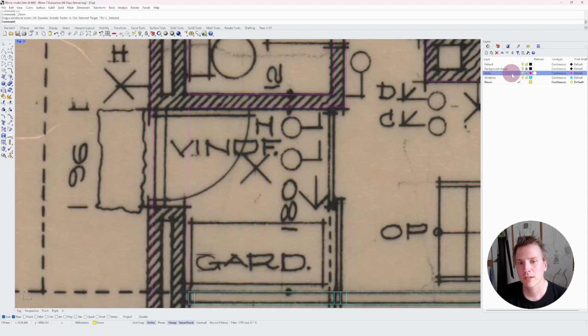To do that, I'm going to double click on the walls layer and I'm going to draw a line from this wall to here. And then I know that the dimension of the door is 96 centimeters. So I'll copy that one, and I'll drag down here and I'll type 96 and enter. And then I will click and escape to cancel. So now we have our hole marked.